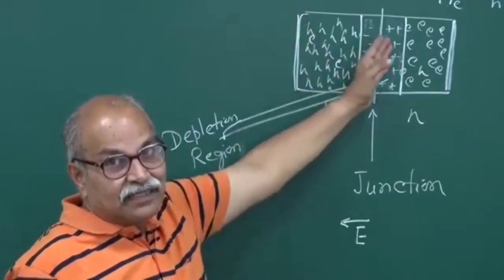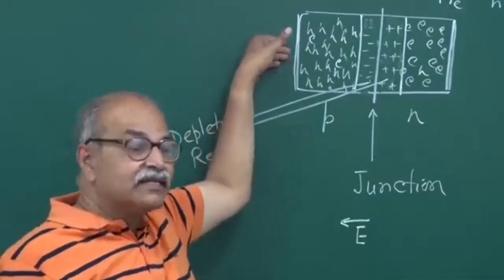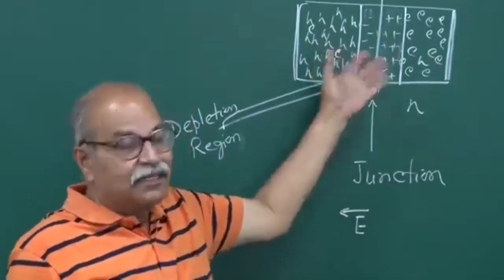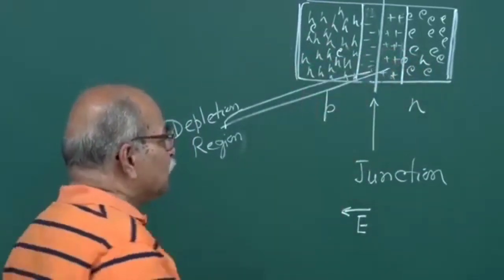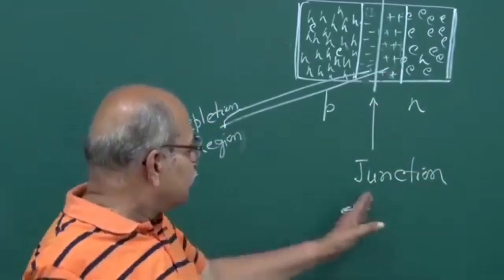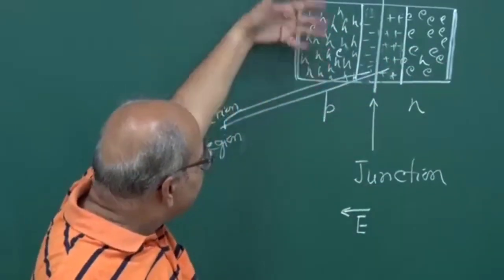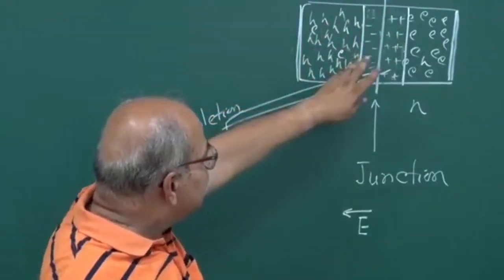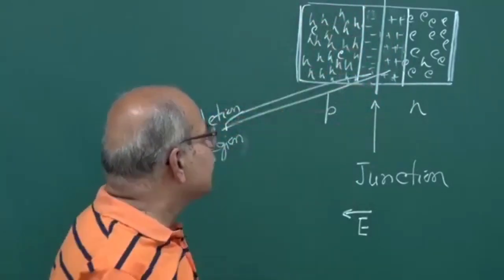Of course, you have metallic contacts, and again you have a potential difference at each contact. So finally, if you see from outside, no potential difference will appear between this connection and this connection. You cannot light your lamp because of this potential difference. But inside this material, yes, a potential difference is created. And if you look at the energy, the electron energies are opposite, because it's minus e times V. So here the electric field is in this direction, the potential here is smaller and the potential here is larger. But if you talk of energies, these energies will be up and these energies will be down. So let me talk today about a relation between this width and the potential difference, the electric field, and all those things. Let us make some calculation on that.